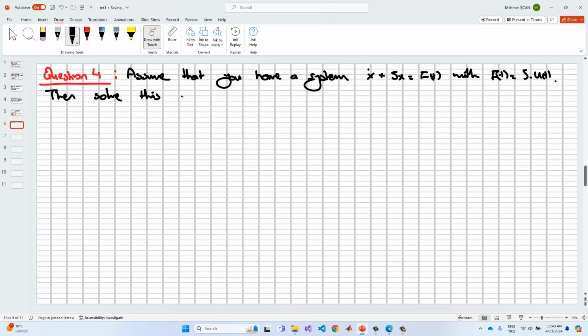this output using the convolution integral. Okay, the solution can be given as follows. We must firstly find the impulse response for this system, because we have the dynamic equation here just like this one, and then we need to apply 5 times u(t) as f(t) to this system in order to take the output results. Okay, and so